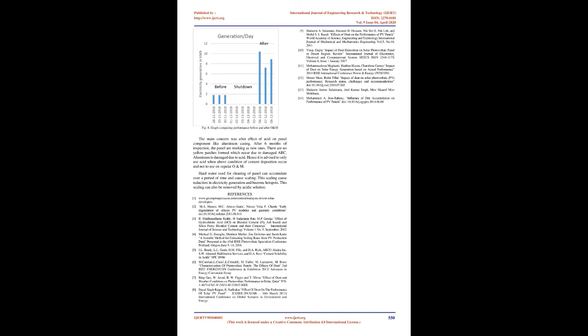Hard water used for cleaning of panels can accumulate over a period of time and cause scaling. This scaling causes reduction in electricity generation and becomes hot spots. This scaling can also be removed by acidic solution.